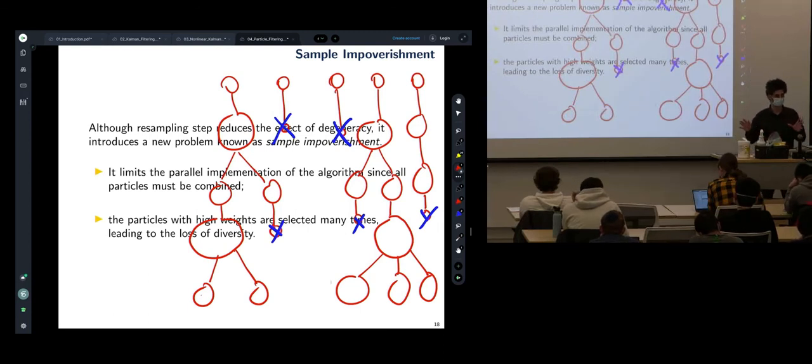Yes, there are many variations of the algorithms, including in your textbook. You can use KL divergence and some other methods to adapt the number of particles. Probably in the beginning you want more particles because you're trying to bootstrap or initialize the filter, right? Once you are around the most likely hypothesis, maybe you just need a smaller number of samples to track.